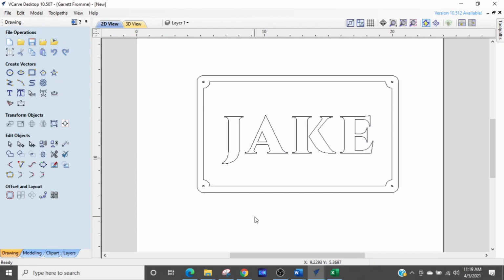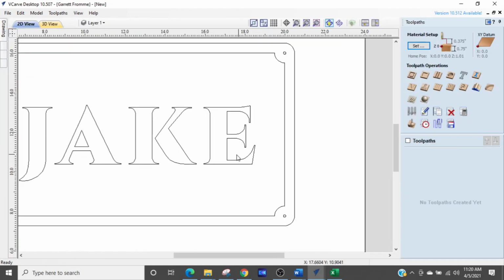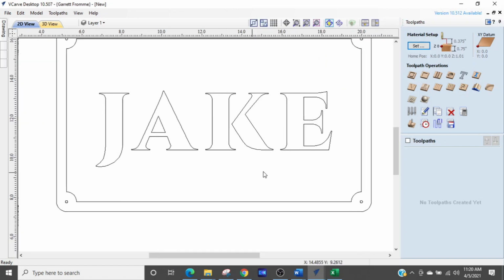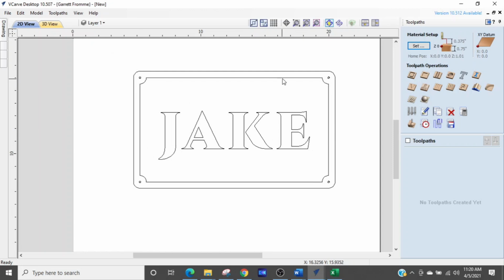Jake, I should just give this to you. We'll run a quick toolpath. For all intents and purposes, this video is done to answer how you do radiuses. But I'm just going to generate a quick toolpath on the sign. So what we're going to do is we're going to recess the rectangle, and we're going to let Jake pop out. So we're going to select from the rectangle and into Jake. So now we have that done. We're going to do a pocketing cut.